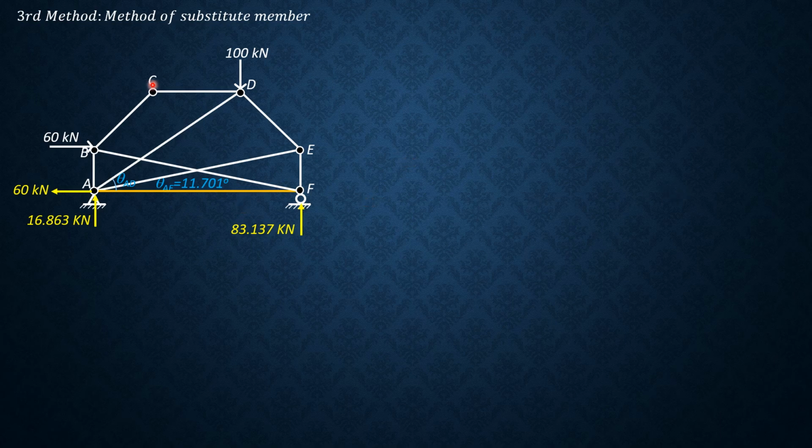So from there, you can solve for the force of member CF. Then, since all other members have forces in the first phase added to the force in the second phase, which is in terms of CF, and CF has been found, then you can determine the forces in all other members. So that's the procedure. So let's proceed.